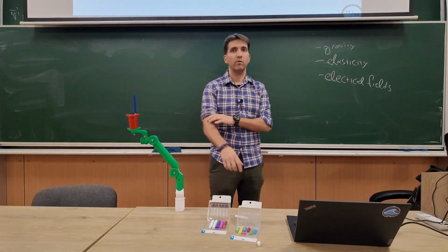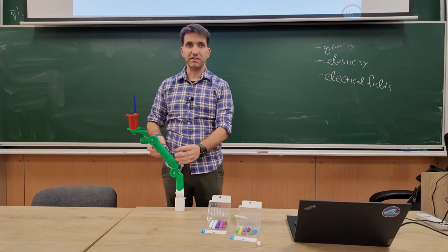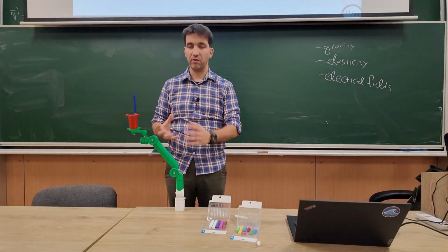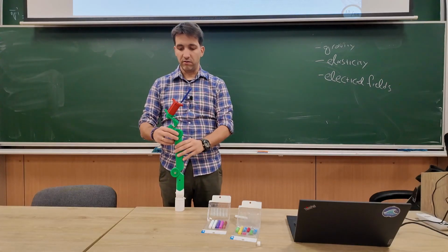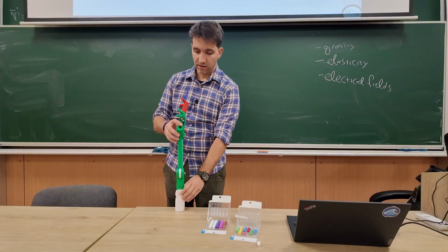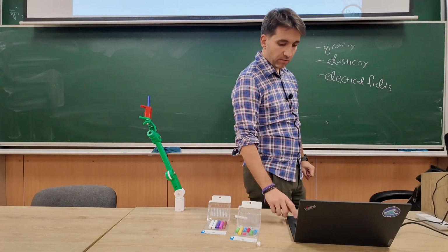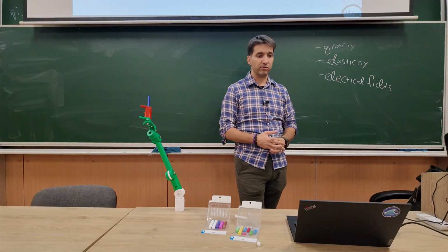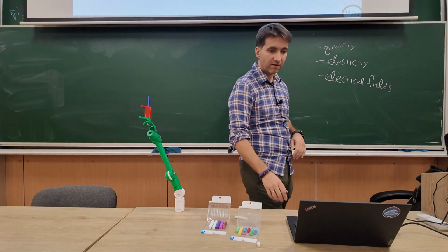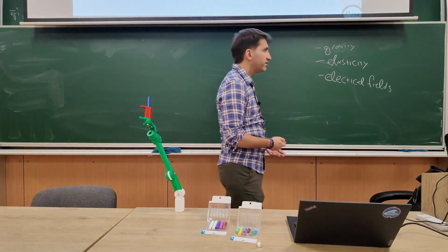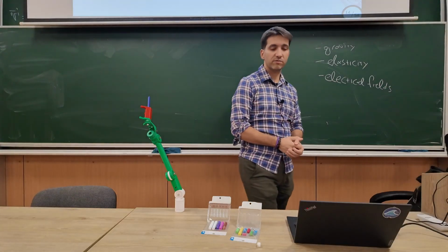So we do consider this important, because this robot has masses that move in the gravitational field, and based on their positions, they will have an effect on the potential energy of the system. Like this robot will have a different potential in this configuration than in this configuration, whatever. And we'll see what the potential due to gravity is. All right. So the most common source of potential energy for robotics is the gravitational field of the Earth. Unless we're doing Mars robotics, then it would be the gravitational field of Mars. Anyone remembers how we calculate the potential? What is the formula? mgh.